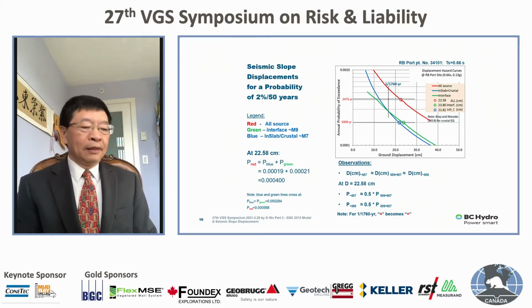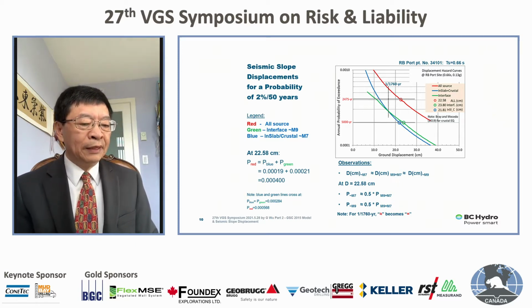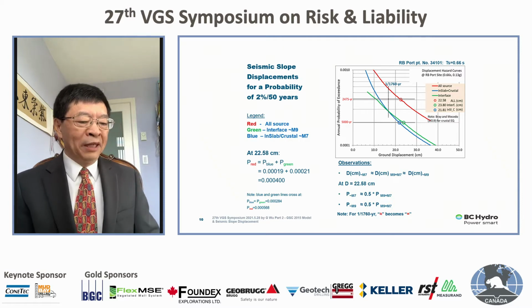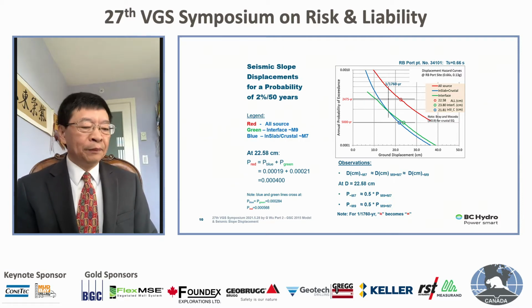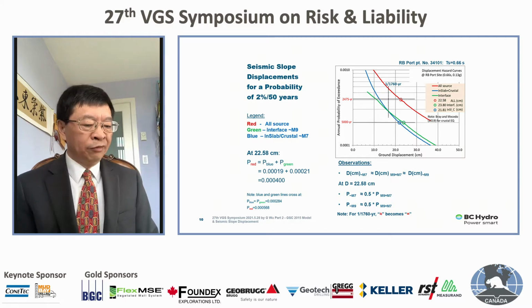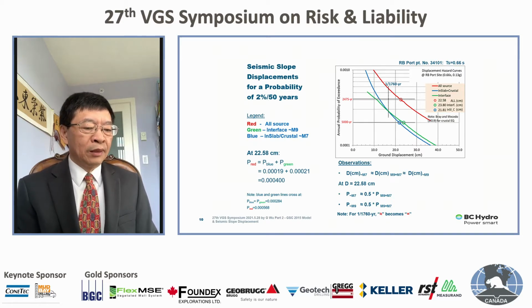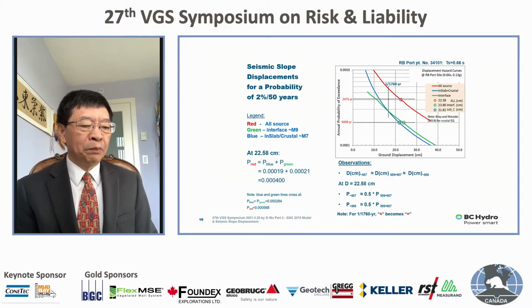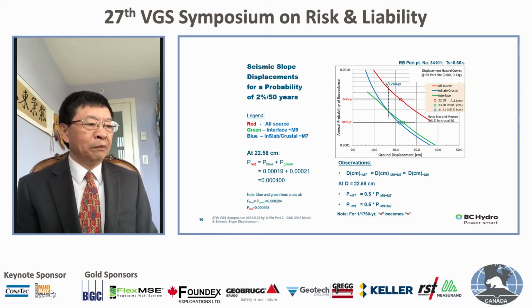Now here is how you would do that using this PSPA method. First of all, you derive a complete curve using the crustal earthquake equation by Bray. So you will derive this line, the blue line in the figure. The blue line in the figure is using the 2019 crustal displacement equation by Bray, and you apply the spectral values at different levels.